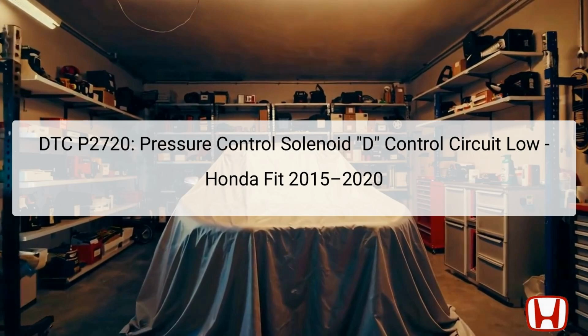The Diagnostic Trouble Code P2720 indicates a problem with the Pressure Control Solenoid D control circuit in the Honda Fit models from 2015 to 2020. This code specifically points to a low electrical signal from the solenoid circuit, suggesting that there is an issue with the electrical connections or components involved. As such, it's important to note that this code does not indicate mechanical issues within the continuously variable transmission, CVT